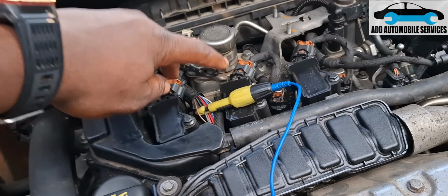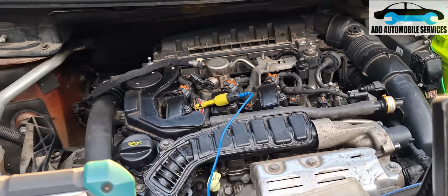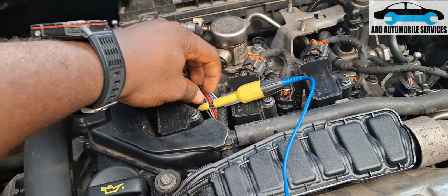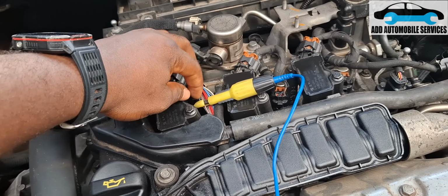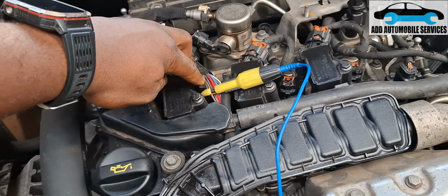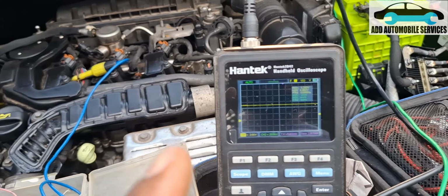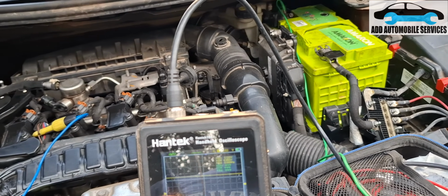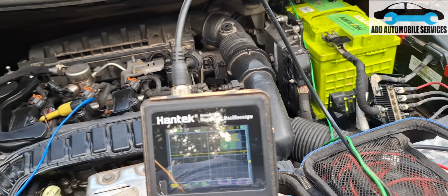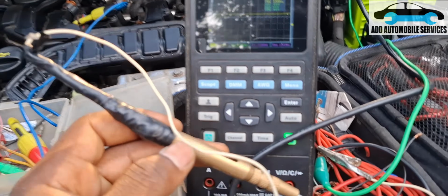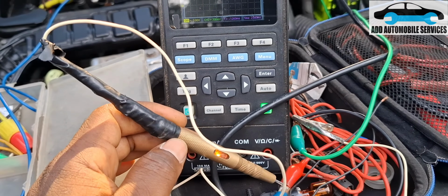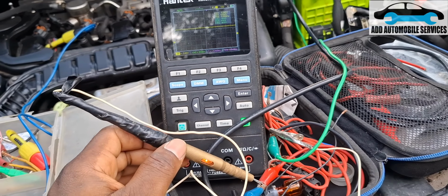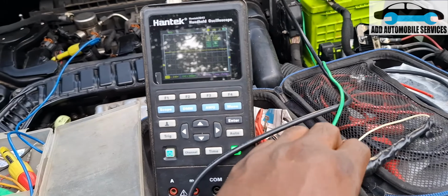Now I have to test for power and see if I'll find my power line. I'm now on the brown line, and I've already tested continuity from the sensor to this side. This brown line is also giving me 5 volts. So I have to test and see if it will turn on my test light. It's able to turn on my test light, and you can see the voltage is not dropping that much. My test light can be turned on with 5 volts. So that tells me that is a power line.